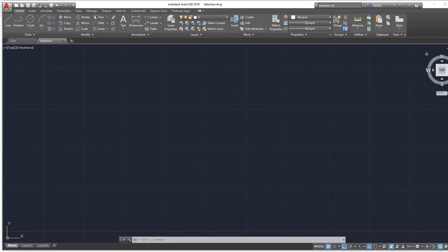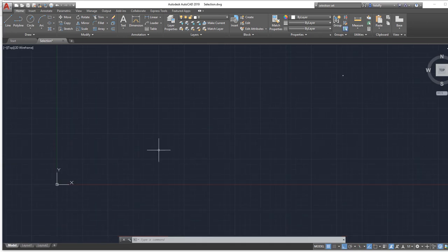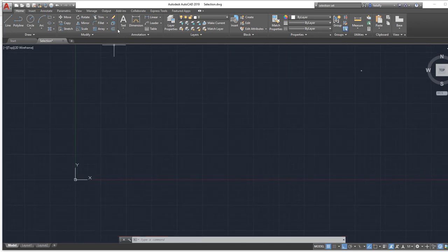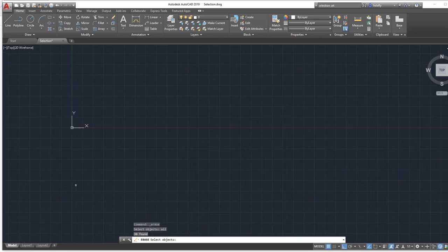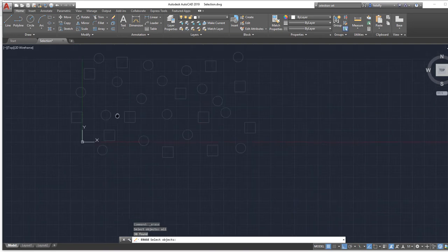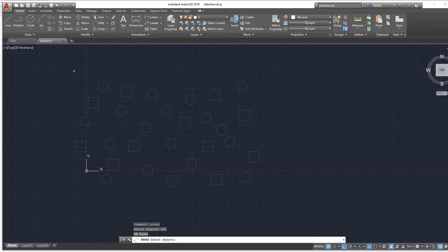And what's happening is you've got some object up here. You can see it here, this circle. Sometimes it could be a bit of text with a full stop, which is tiny, and you just don't see it. One thing you can do here, and this is where I usually use it, is erase all, return. Don't right click to complete the command yet. Zoom into the area you want, R for remove, do a window around your main drawing and select it.